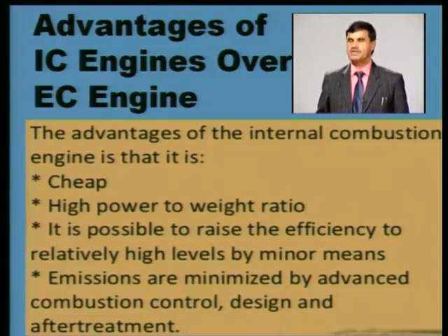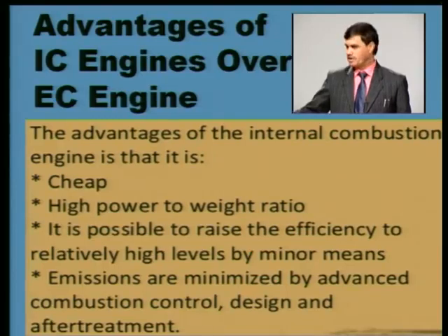However, in some exceptional external combustion engines, the efficiency is higher than internal combustion engines. Even exhaust emissions in internal combustion engines are controlled up to a certain limit by controlling the spark timing, the compression ratio, and by changing design parameters. Even treatment of the exhaust is being done, so that exhaust emissions are controlled